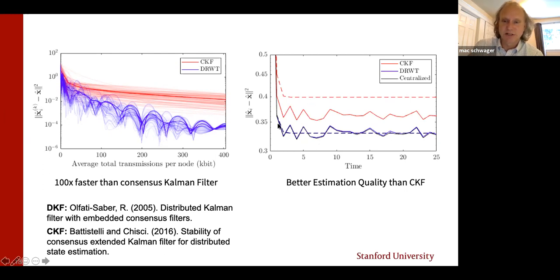On this plot, I show the fully centralized, God's eye view, with all data in one processor, results computed with a Kalman filter. You cannot do better than this. This is as good as can be done. And that's the black line. You can see a blue line that's floating just over the top of the black line. That's our filter, the distributed rolling window tracker.